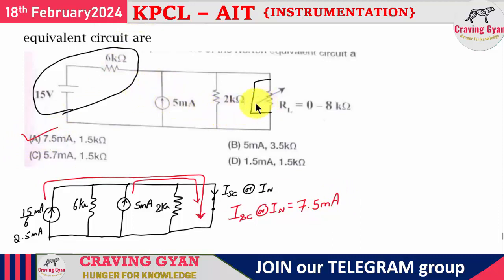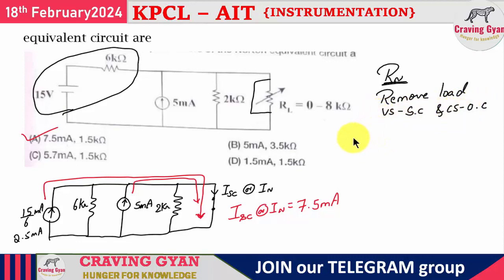If you want to find the Norton equivalent circuit, what you are going to do is remove the load. So this Norton resistance, how you are going to find it: first thing, remove the load. Then all the voltage sources need to be treated as short circuit, and all the current sources need to be treated as open circuit. Look at the things. Current source is there, I have treated it as open circuit. Then you will be having 6 kilo ohms. Then you will be having one more current source, open circuit. Then you will be having 2 kilo ohms.